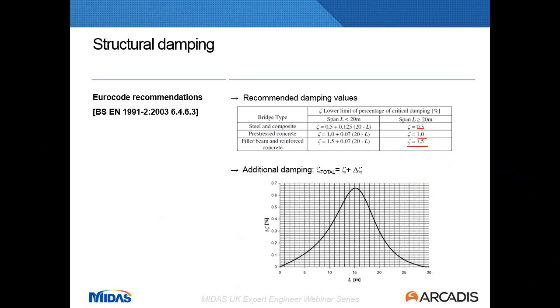Time integration means that you just check the balance equations and you solve the stiffness and mass matrix at every time step. And that means that you can consider any kind of analysis, linear, non-linear, any kind of properties. So it gives you more flexibility on how you consider your model.